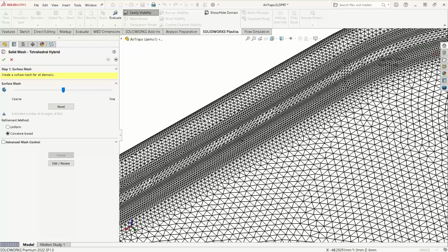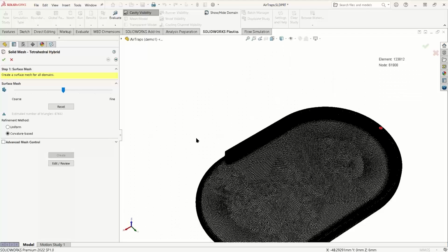So maybe it's more or less too much. In such case, if you are in pre-design and you want to deal with fast simulation, you can take this cursor and start with a coarser mesh. But for the demo purpose, it's just to show you how to deal with the mesh. So once this mesh is saved, you are ready to run your first simulation.